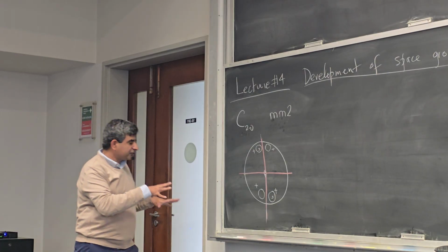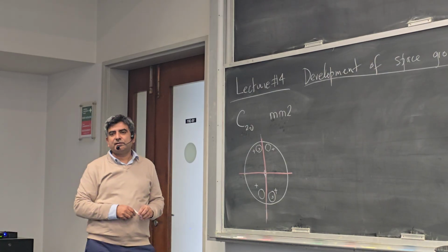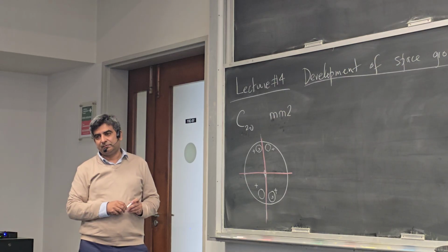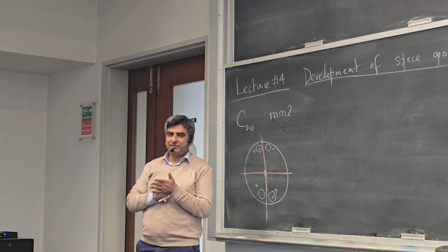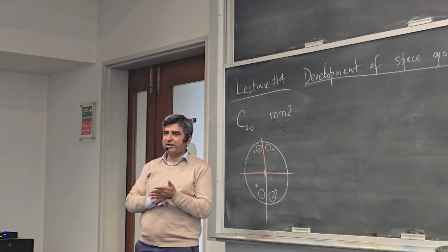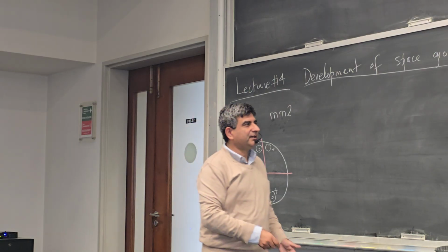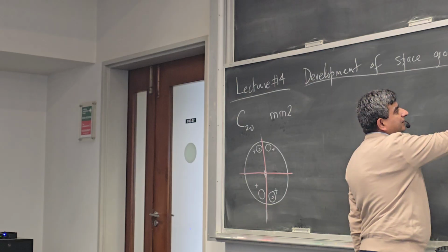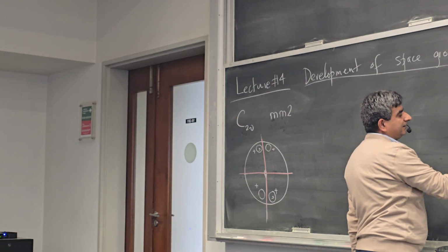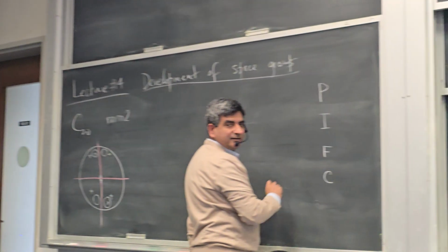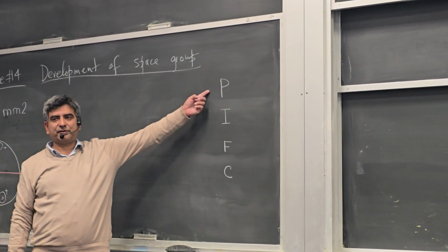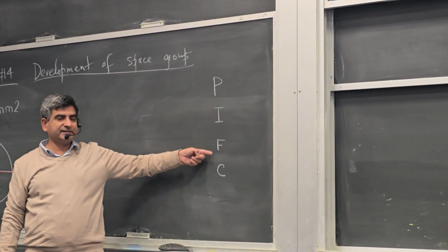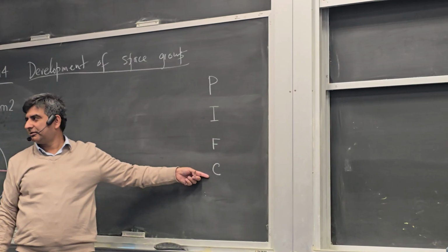Alright, so now let's draw an orthorhombic crystal lattice. Actually there are 4 kinds of orthorhombic lattices. If you do the centering, there are 4 Bravais lattices associated with orthorhombic. There is the P, there is the I, there is the F, there is the C. So you could have 4 kinds of centering: no centering at all, primitive, body-centered, face-centered, and C-centered.